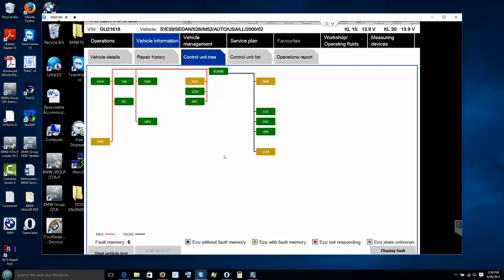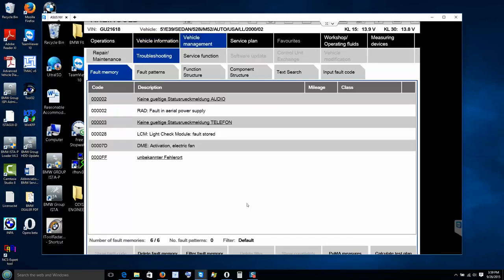All right. Everything is green now on the DSC. The fault code is gone. What do you want to check out on this car now? Well, I don't know. I was just looking at it, and these rear lights are on, showing that the bulbs are blown, but you have aftermarket lights in it. So in the cluster, there is a light on to say that the bulb in the back is blown, right? Yeah, it's showing the two bulbs in the back blown.